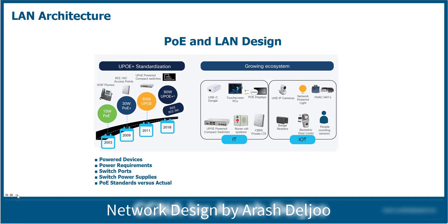You know that in one switch, okay, maybe we can provide 15 watts of power in each port, but this switch has a specific capability. For example, it can supply up to 100 watts of power. This means that only 6 ports or maybe 7 ports of this switch can supply the power. Maybe you have devices with 15 watts of requirement, it's okay, but because you have, for example, 10 devices with 15 watts requirement, you need 150 watts of power.